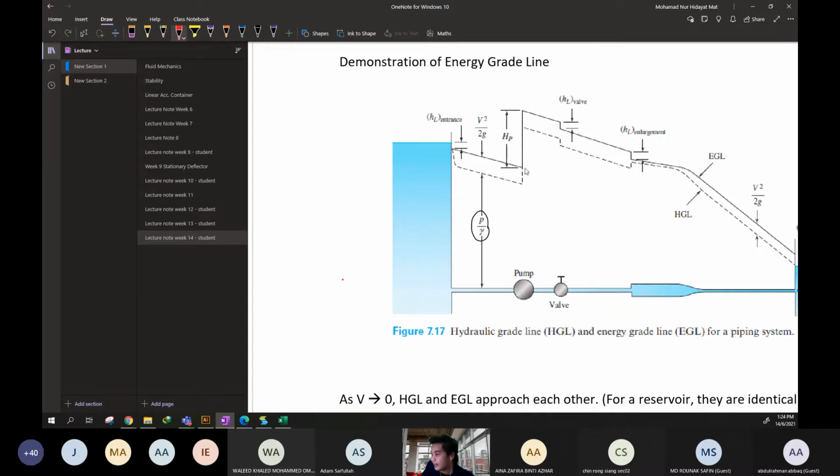And then after that, going out of the pump, the pressure drops. Due to why? Why is there a slight drop? Minor losses, doctor. Minor or major? No, major, because they are linked. Major, all right. The friction along the pipe is the major loss. The bending of the pipe, the geometry change, is the minor loss. So this is the major losses. This is the major losses. This is the minor losses.